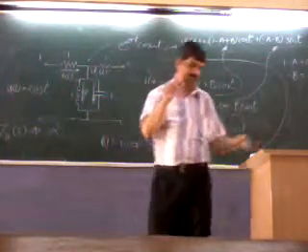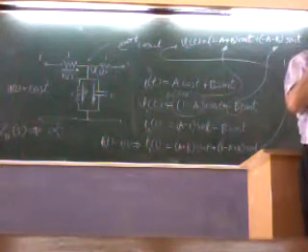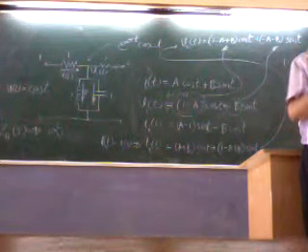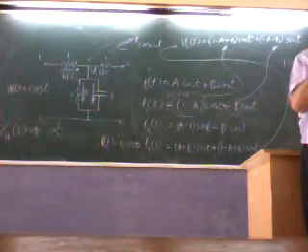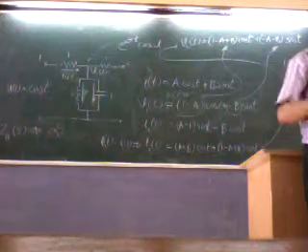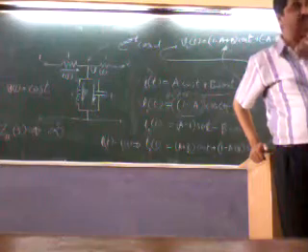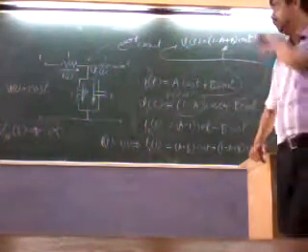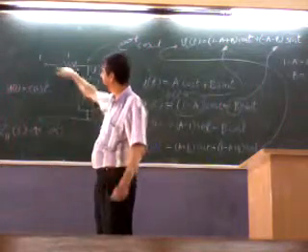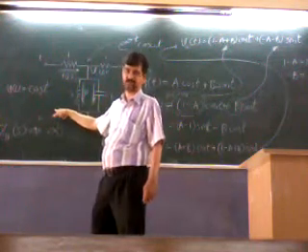So we have started for the values of S for which we will be getting a pole of the function, meaning the value of Z11. What is Z11? It is a driving point impedance, the ratio of voltage upon current, and for Vt equal to cos t we find that no current flows, so it's a pole of the function.